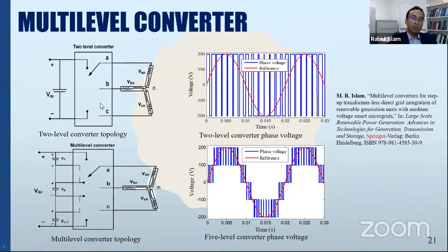People are using this topology to develop high voltage DC converters, right? So what's the problem with that? They actually connect a number of IGBTs in series, right? Then they apply high voltage here. But in this case, there are some serious issues, because all the IGBTs will not have the same characteristics, operating characteristics, internal resistance or internal parameters. So it is very difficult to avoid mismatch, and definitely there are some issues there. But those problems are not really considerable for multi-level converter applications.